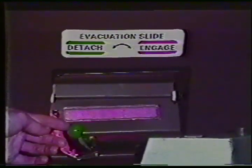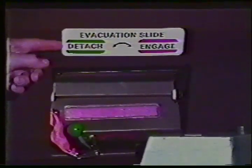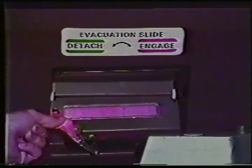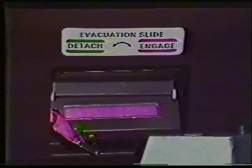First, familiarize yourself with some of the door's features. At approximately the center, there is an arming lever under a clear cover. This lever will either engage or detach the slide bar as indicated above. Whenever the door is in detach, notice this red pin flag. This means the door may be opened without deploying the slide.